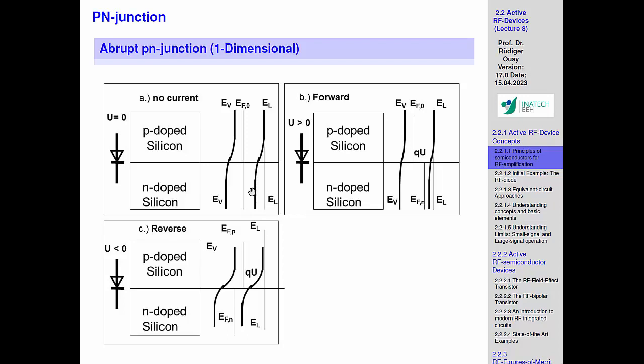So in the case of the p-type, the conduction band goes up, and then in the n-type silicon it goes down, and then we can now vary the difference. So there's a depletion layer formed between them, because when they touch, there's a diffusion of the carriers inside the region, they recombine, and there's essentially a region where there are no free carriers available, which is a good situation.